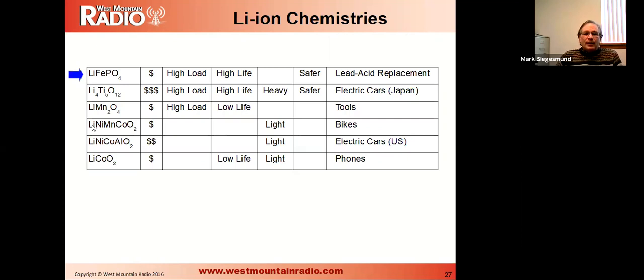It's also considered very good for an instantaneous high load. So you start to draw 20 amps out of that battery instantaneously when you transmit. The iron phosphate is going to be a much better battery at dealing with that. But there are lots of technologies, and like I say, they come out with new ones every year. I know there's one kicking around right now. It's basically iron phosphate, and they've added a little bit of magnesium in there. And those seem to be just about as good as the iron phosphates as well. But yeah, I would stick with the LiFePO4 batteries for amateur radio.